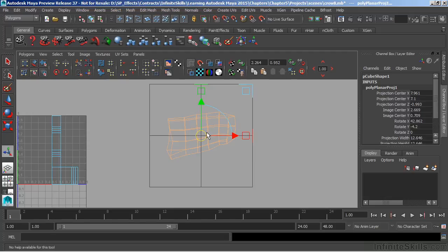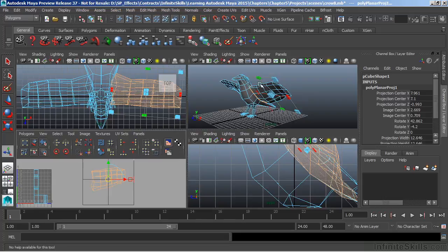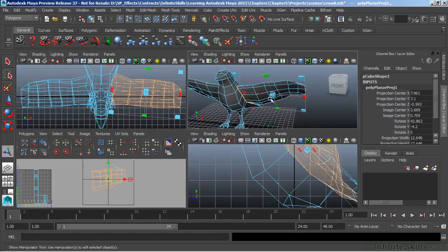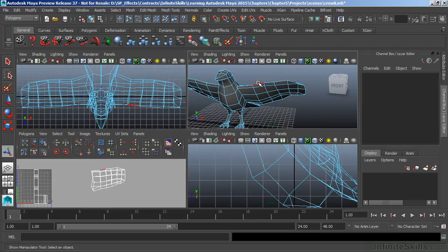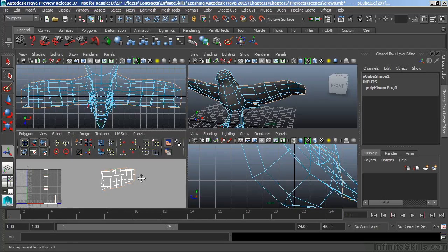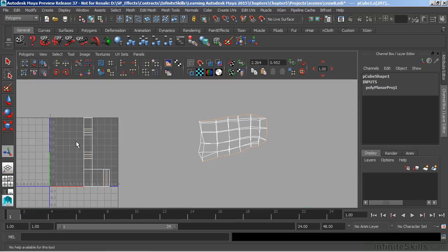Now, when we did this projection, we projected both the front and back. So I need to break these up so that I have a definitive back and front. I'm going to go out to my model where it's a little bit easier to make this selection and just go to Edge and double click the dividing line that separates my wing in half. So I'll just double click that. That'll give me an edge loop going all the way through the model, giving me a lot of extra edges that are being selected there. And you can see those here.